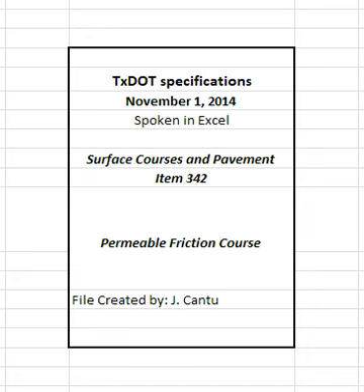4.5.2 Mixing and discharge of materials. Notify the engineer of the target discharge temperature and produce the mixture within 25 degrees Fahrenheit of the target. Monitor the temperature of the material in the truck before shipping to ensure that it does not exceed 350 degrees Fahrenheit, or 275 degrees Fahrenheit for WMA, and is not lower than 215 degrees Fahrenheit. The department will not pay for or allow placement of any mixture produced above 350 degrees Fahrenheit.